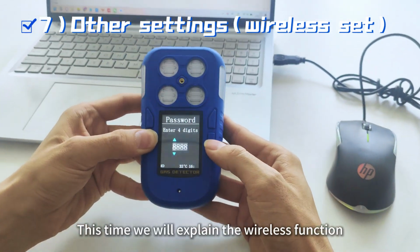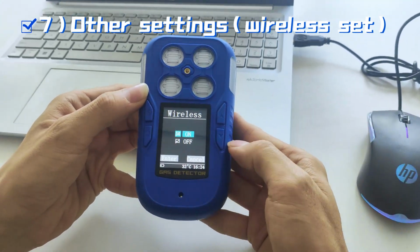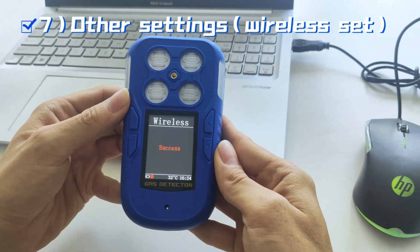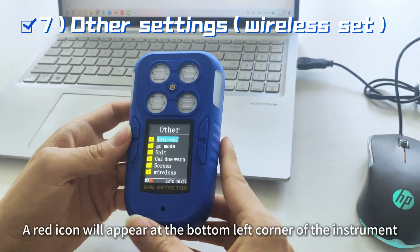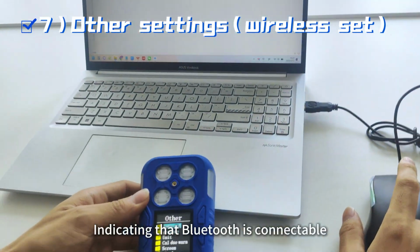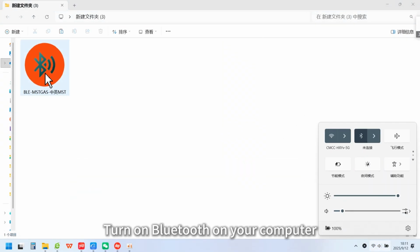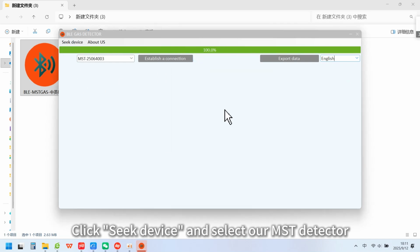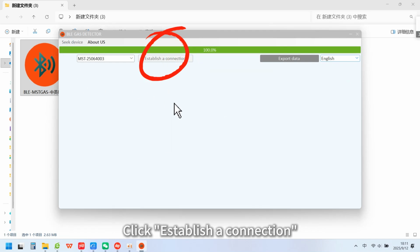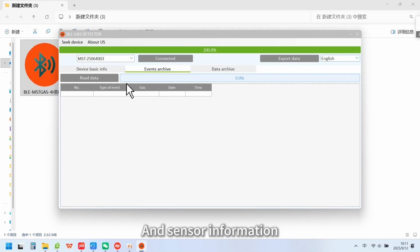This time we will explain the wireless function, namely Bluetooth connection. After turning on the Bluetooth function, a red icon will appear at the bottom left corner of the instrument, indicating that Bluetooth is connectable. After installing the included software, turn on Bluetooth on your computer. You can switch to English in the upper right corner. Click Seek Device and select our MST detector. Click Establish a connection. Click Read and you can view the instrument's parameters and sensor information.